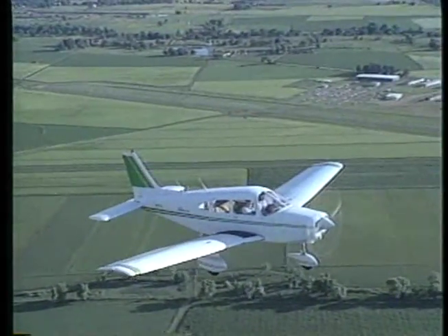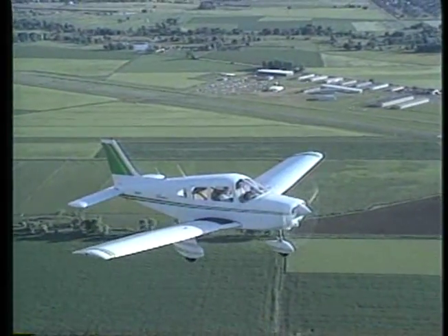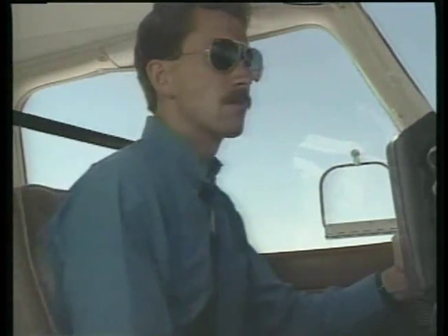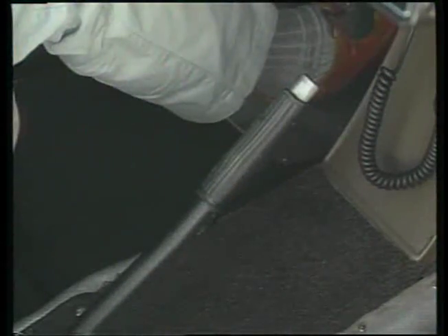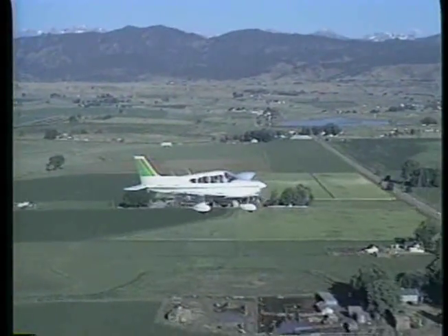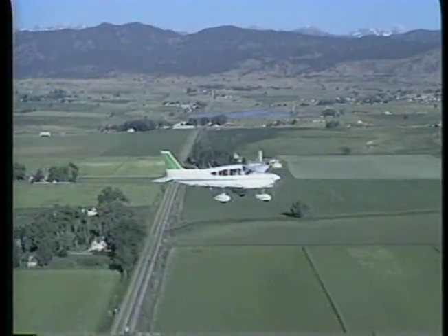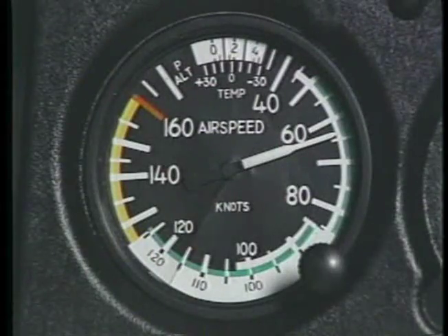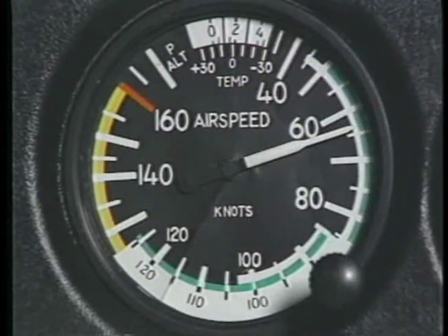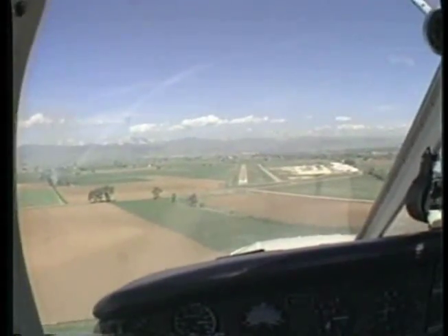As you enter the traffic pattern and complete the checklist, you need to concentrate on performing a stabilized approach with a smooth, soft touchdown. Using full flaps during a soft field landing will help you touch down at a low airspeed. They should be applied smoothly during the downwind, base, and final legs of the approach. Your objective for a soft field landing is to transfer the airplane's weight from the wings to the landing gear as smoothly and gently as possible. The final approach airspeed that you use at a soft field is normally the same as that used for short field landings. The descent angle will depend on whether or not any obstructions are located in your approach path.